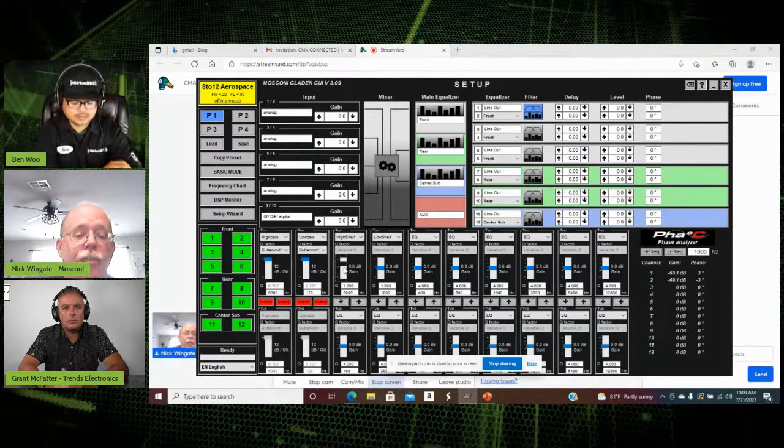Now that will raise every frequency from 5,000 hertz and up 6 dB. Now there's going to be that roll off we talked about, and it'll be there. So from 5,000 hertz to about 10,000 hertz, we're flat, and it doesn't affect phase. That's the beauty of this. It affects the output or amplitude, but it doesn't affect phase.